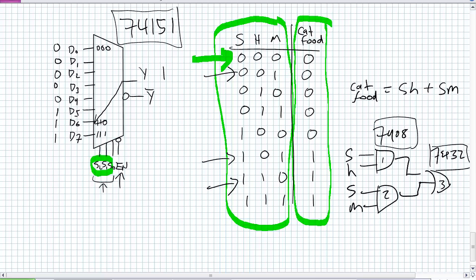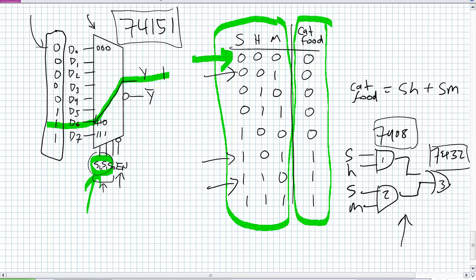And this is exactly what a field programmable gate array is doing. In contrast to a CPLD, the programmable logic device previous to the FPGA, which really did implement the SOP expression, a field programmable gate array uses memory, which you created using your VHDL expressions. It basically takes the output of that SOP expression and puts it into memory. Then it uses a data selector. I know it's not using a 74151, but it's using a data selector, and these are your inputs. All it does is route the appropriate memory position, in this case this one, to the output. If those inputs change, the data selector goes to a different location within your memory.